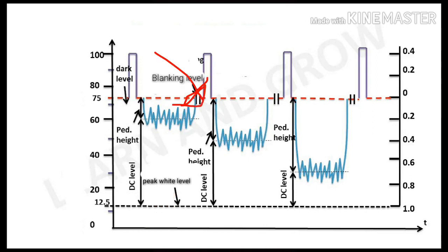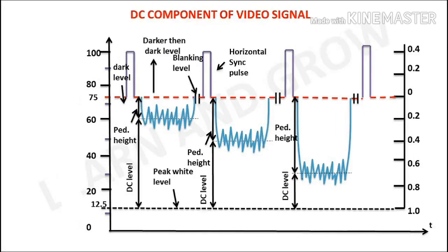Starting at the left in figure 7.7, the last 4 horizontal viewing lines at the raster bottom are shown along with the required horizontal alignment and blanking pulses. Immediately after the last visible line, the video signal is made black by a vertical blanking pulse in preparation for retrace of the vertical trace.